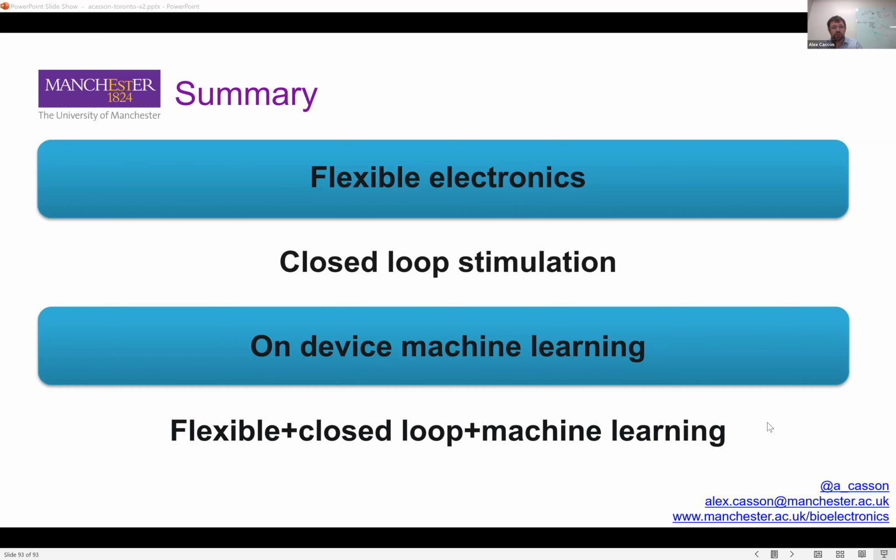Of course, those two interact if your electrode is going to spread and push the legs apart. In general, you will get better performance if you've got more contact area and if you push the electrodes in harder. Both of them are roughly linear. So if you push in twice as hard, you can get about half the contact impedance.